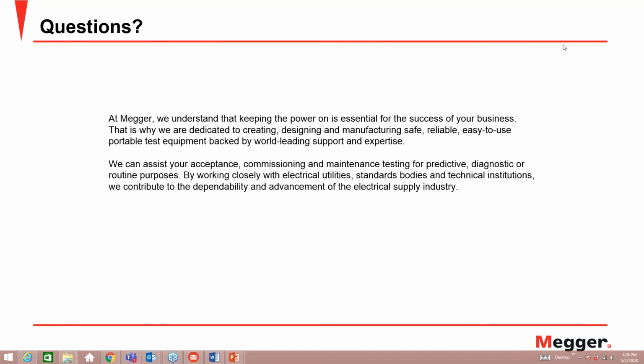All right, thanks, Volney. St. Kit, the next question is for you. How do we properly do a float current test? So as I mentioned earlier, float current is a small amount of DC current which flows through the battery when it's in float condition. If you have a way of measuring the DC current, typically the charger itself shows you the float current on its display, or if you have a DC clamp-on, which you can use to measure a current in milliamps, that can be used.